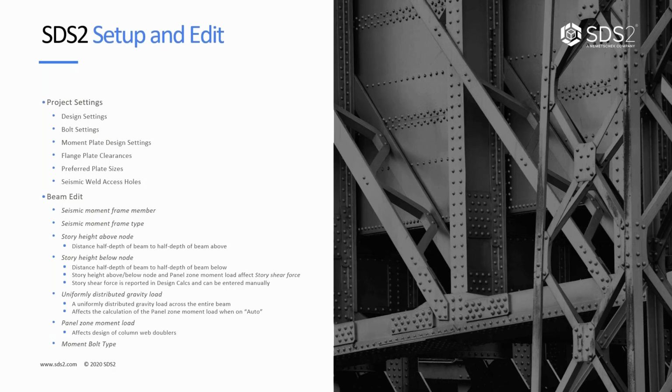So project settings, under our design settings, we have a seismic moment frame checkbox to turn that on by default, and then below there we'll see a type of moment frame, whether that's OMF, SMF, or IMF. Our bolt settings, so we have default bolt settings for our moment bolts and such.